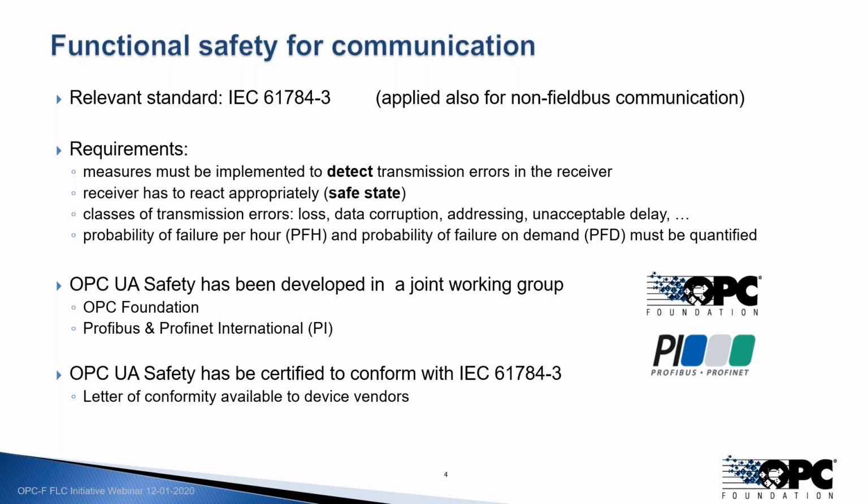This typically means that the receiver is switching into a safe state. So if the receiver is a brake system, that safe state typically would be to enable the brakes, stop the system. Or if it's a circuit breaker, then typically this would mean open the circuit or something like that.